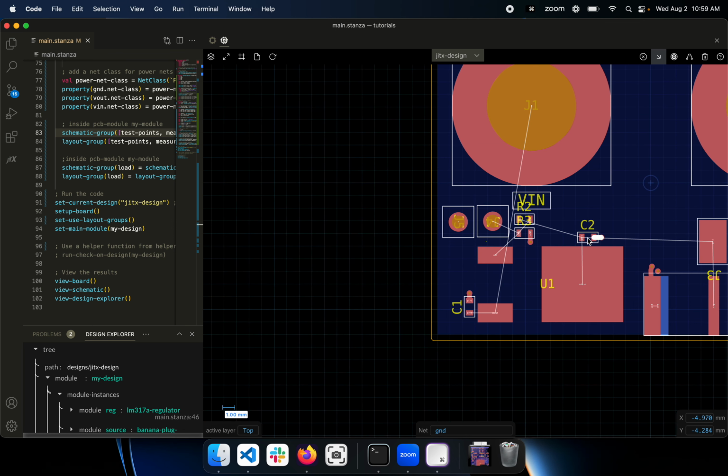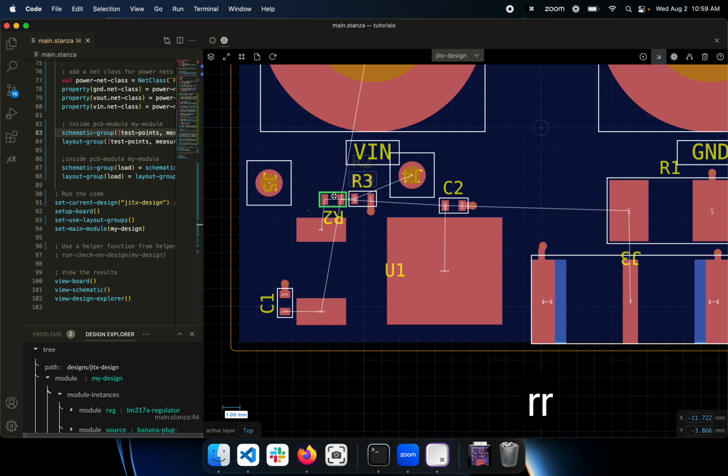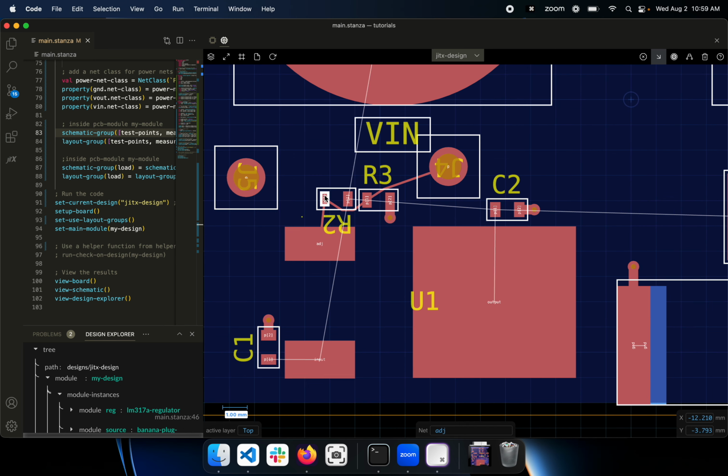And notice that when you move a component, its via moves with it. So this is for very quickly building assemblies of things. And I don't need you. Okay. Now this, I like this, so I'm going to move this here. And let's say I want to route this net. So I do just have a selection, hit Q. So here I hit a pad, hit A, select all pads in the net, hit Q.